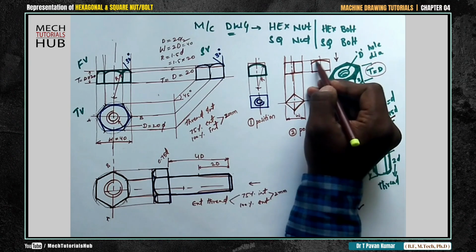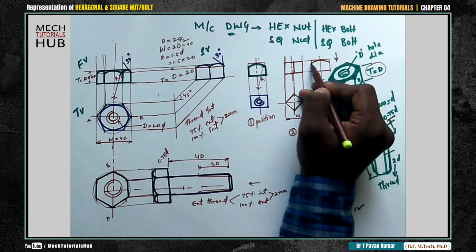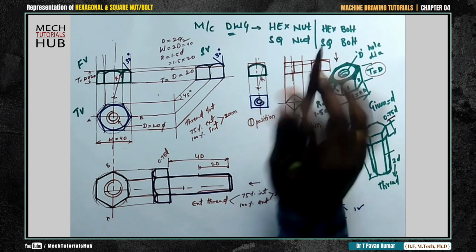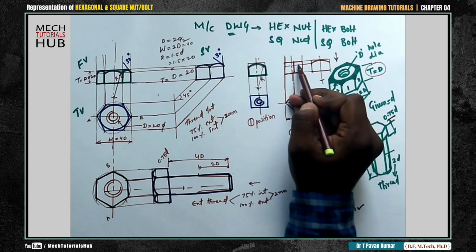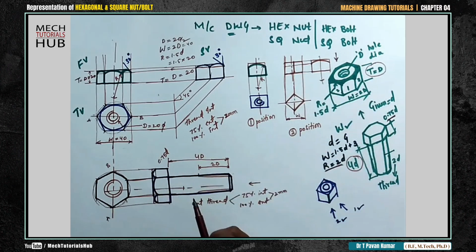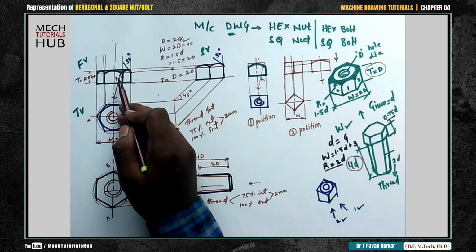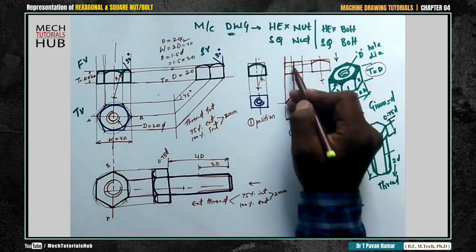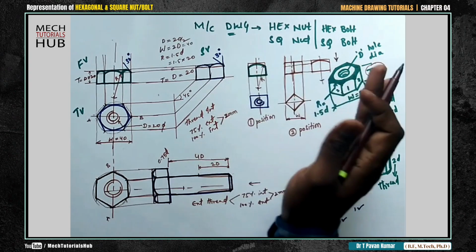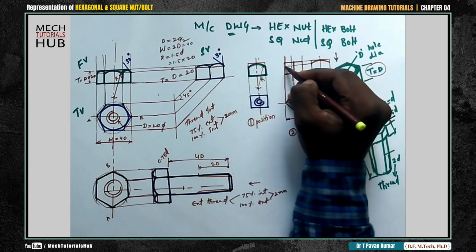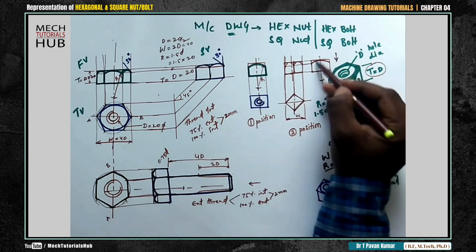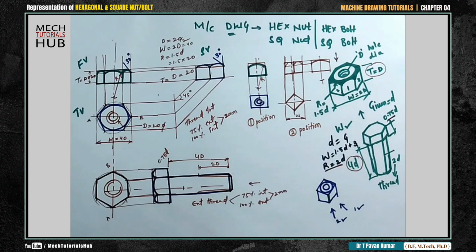Now wherever this curve got intersected with the next vertical, take that projector line onto the front view. Now you got these two boxes. Ultimate aim is to get these two boxes to place that 30 degrees inclination. That is what we did from the hexagonal nut bolts till this particular point. So now we got two reducer length boxes. Align your drafter to 30 degrees inclination. Go to the intersection and draw those 30 degrees lines. We have drawn this true shape to get these two boxes, or to get this width. That is the only intention.